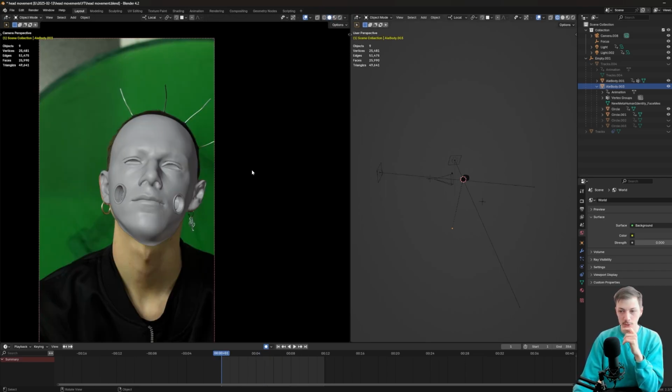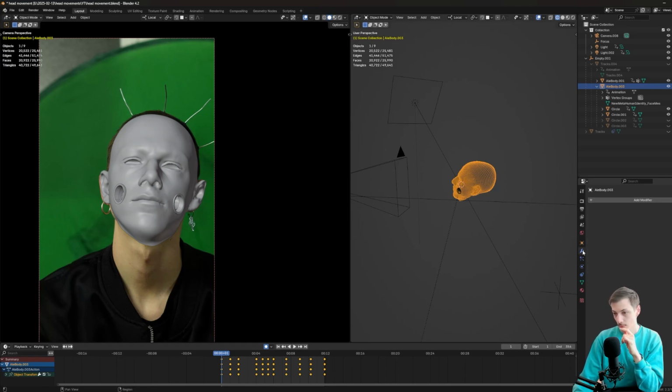Two things have to be done. One is to project the footage on the face. We select the face, modifiers, edit, UV project.